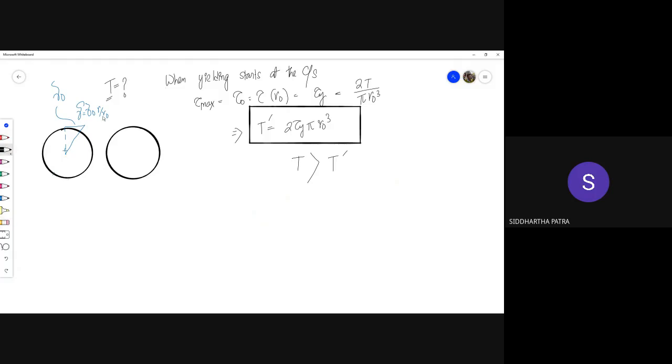So you can see shear strain is changing proportional to radius. And this is the relation between shear stress and shear strain. Elastic, perfectly plastic. And shear strain is changing linear to r, proportional to r. So how would shear stress change with the radius?